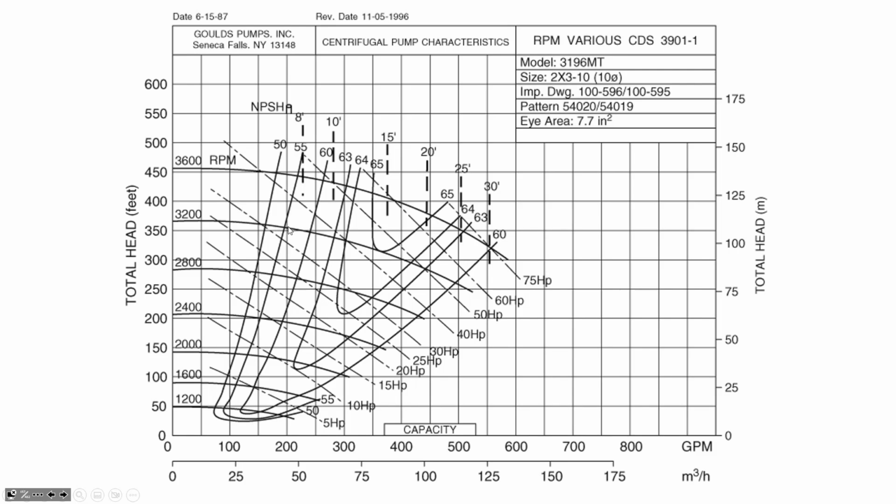It's more efficient, 55% efficient, when it's operating at 190 gallons per minute. And its maximum efficiency for that rotational rate of 3,200 RPM is 65%, and so it's going to be most efficient at translating mechanical energy into fluid energy here at a flow rate of, it looks like, about 360 gallons per minute. So the efficiency of the pump is something that we can get off of the figure.